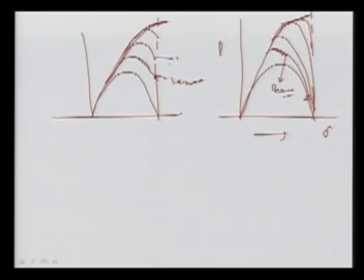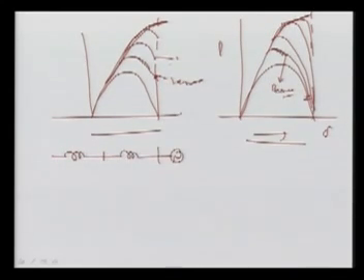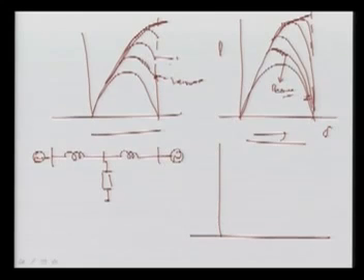Now here also we can say that this device is better than this device in improving the transient stability of the system. How come? Again, for the previous case where I was using the simple fault, let's suppose this is the midpoint, these are the generators, and here we put our SVC or STATCOM. If you remember, now again I can draw this P-angle curve. This is without compensator. If we use a compensator, what happens? Now we can go up to this much.